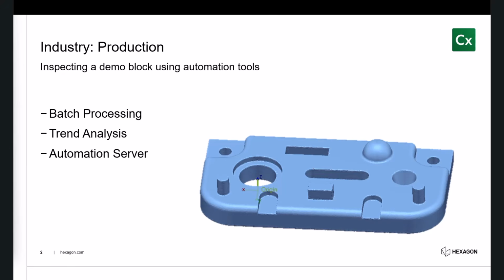So if you're doing some stamping and you're inspecting your stamping tooling, right, everything's still within tolerance, suddenly something's out of tolerance. With that trend report, you can actually see it trend upwards to being out of tolerance or downwards, whichever it's wearing out, and then you can schedule preventative, proactive maintenance. So you're going to replace your tool before you get bad parts. The same can be said for, if you don't know the root cause, you can see where spikes happen.